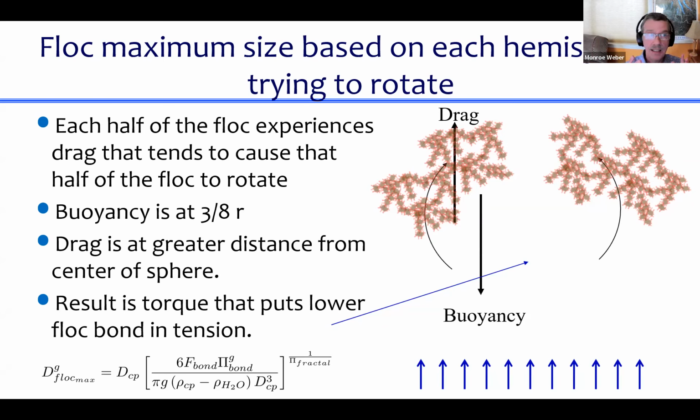And that maximum terminal velocity means that if you design a sedimentation tank where the upflow velocity is faster than the terminal velocity of the biggest flocs, then nothing will be in your floc filter and nothing will be able to get out of the plate settlers and down to the bottom of the sedimentation tank. And that's an interesting failure mode that should be considered.